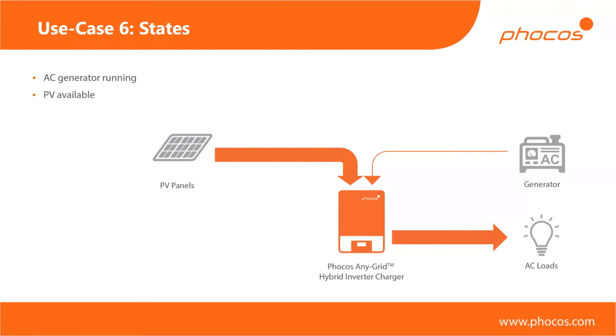Your typical grid-connected power systems will, even if you deactivate grid feed-in, will backfeed for hundreds of milliseconds, and in many cases 20 plus seconds into the grid before actually realizing that they're backfeeding and then reducing the power of the PV side. So that's very important when you're working with generators, that's a very quick process.